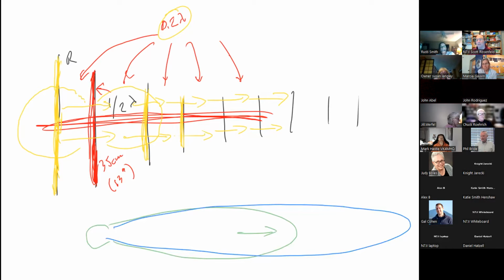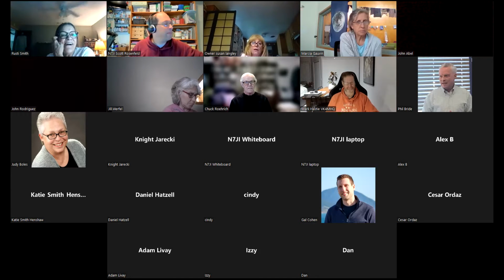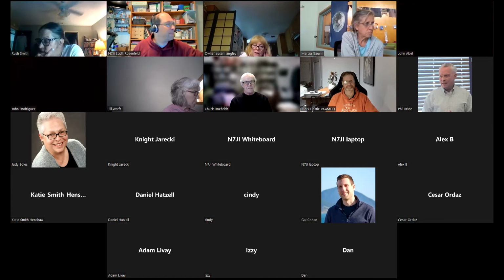For those forward elements, what length should they be? These are typically like 0.48 wavelength, 0.45. There are all kinds of optimized lengths that have been computer modeled, spacing and element lengths. What's cool about it is that if you have a tape measure, it makes it real easy to cut and make them the right length. Yeah. And everybody's got a broken tape measure, right? What did you call that? A Yagi? It's a tape measure Yagi. Tape measure Yagi? Yep.